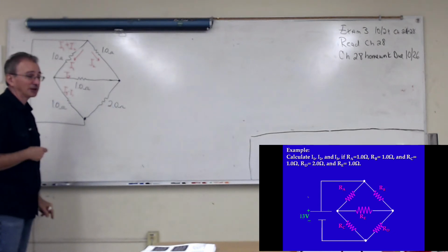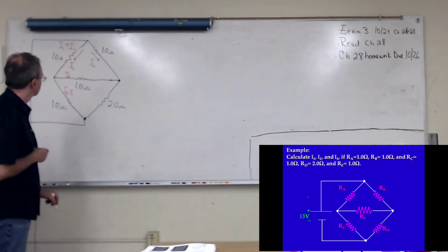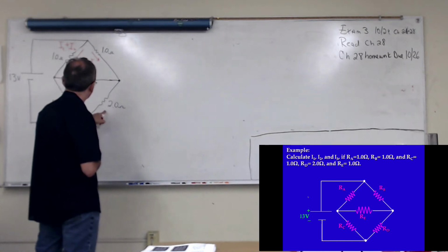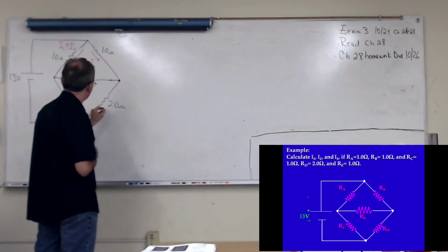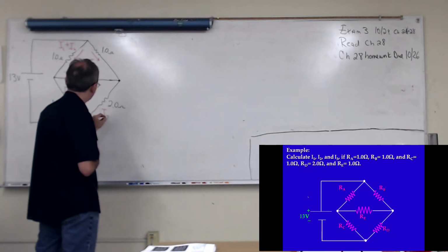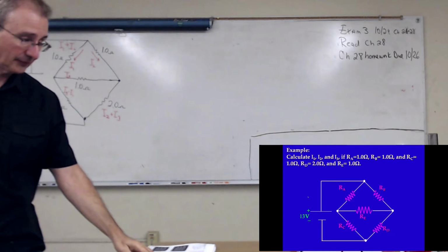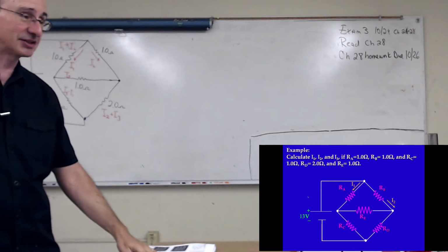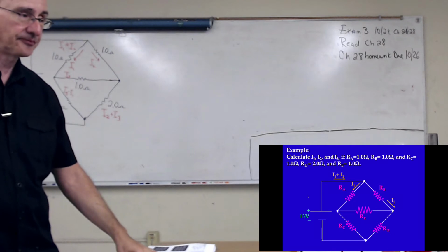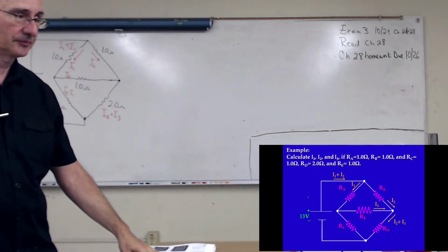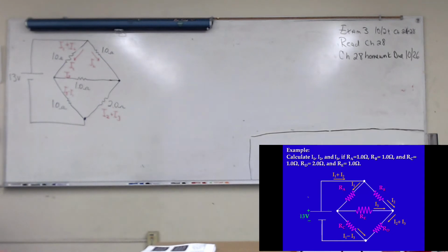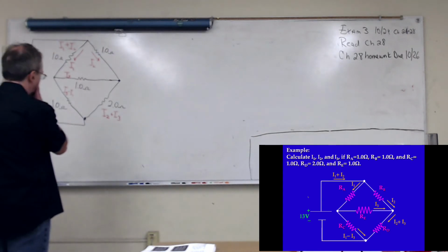Right now I still have only 3 independent currents. And then that means that from that other side is going to be plus the other two, right? Yeah, I2 plus I3. Yeah. So I really have 3 independent currents, so that means I need 3 loops. All right. Once you get to this point, I think the problem gets a little bit easier. The rest of it is just making sure you don't make errors with minus signs. Okay.